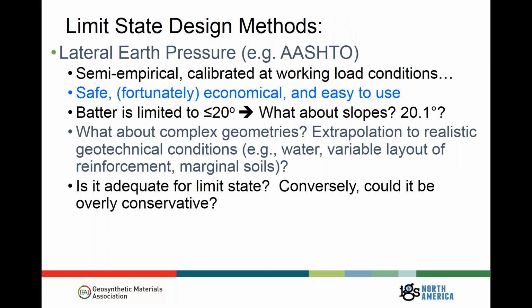The conventional limit state design method that most people are probably familiar with is the one presented in AASHTO. It's basically an earth pressure based approach. For the most part, it's semi-empirical. It's based somewhat on statics, but basically earth pressure theory. But it is somewhat empirical, accounting for, say, the extensibility or inextensibility of reinforcements, basically meant to represent working load conditions, not necessarily the strength limit state.